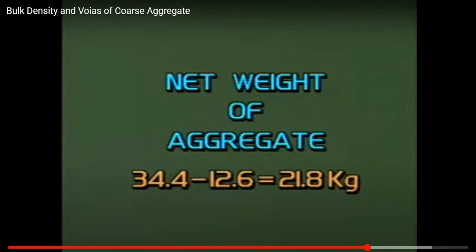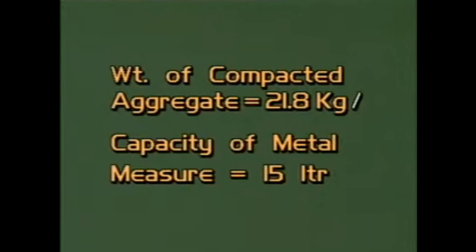34.4 minus 12.6, which is equal to 21.8 kilograms. Rodded bulk density is calculated by dividing the weight of compacted aggregates, which is 21.8 kilograms, by the capacity of the metal measure, which is 15 liters.